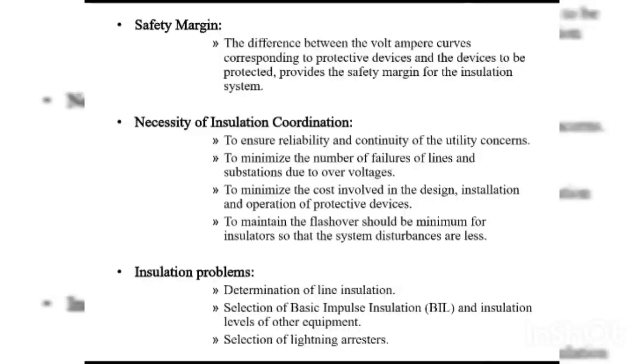Now, let's see the necessity of insulation coordination. The necessity is to ensure reliability and continuity of the utility concerned, to minimize the number of failures of lines and substations due to over voltages, and to minimize the cost involved in the design, installation, and operation of protective devices. Flashover of insulators should be kept minimum so that system disturbances are less.